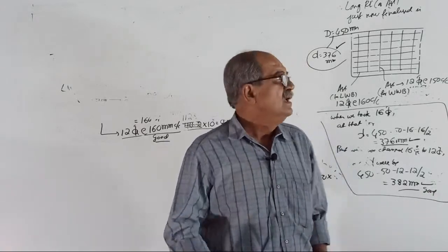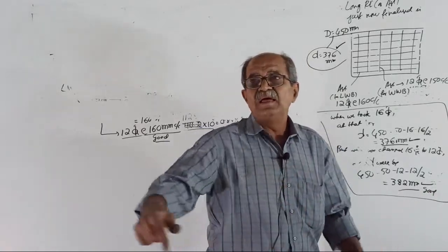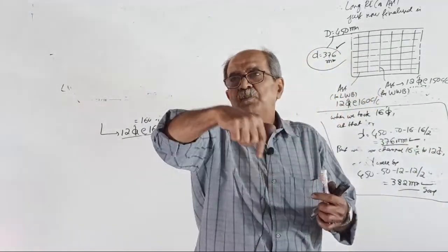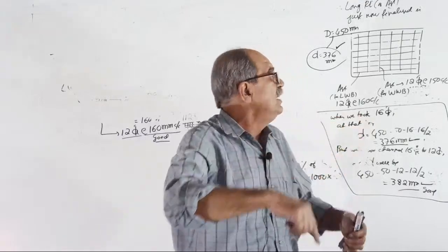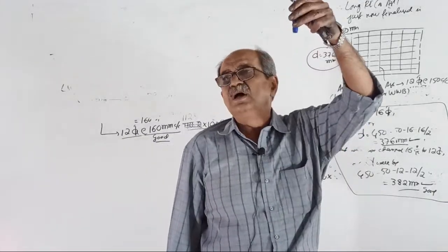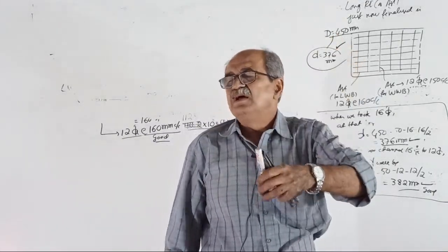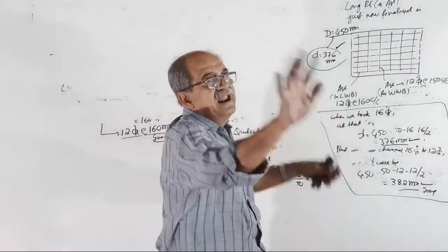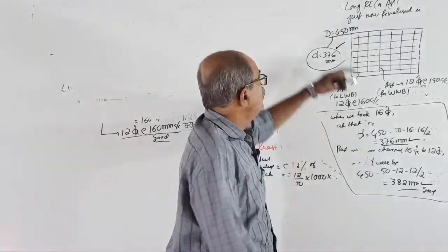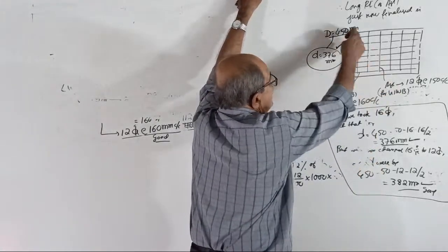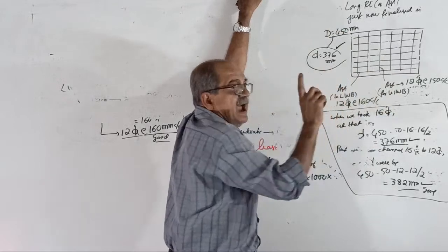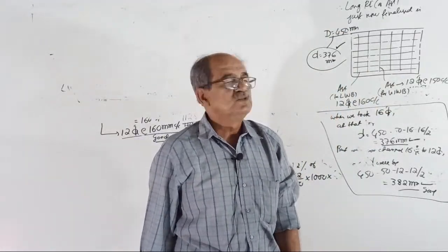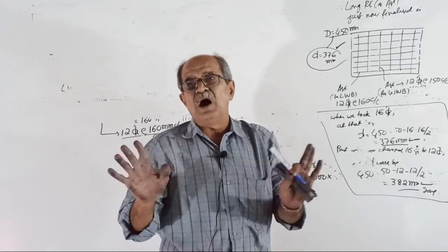What you do is create a model 2.5 by 2.2, place the column 0.23 by 0.55, apply a load of 850 kN. Done. Then run. It will tell you the steel, and also it will tell whether it is safe in punching or not. So punching you need not bother.